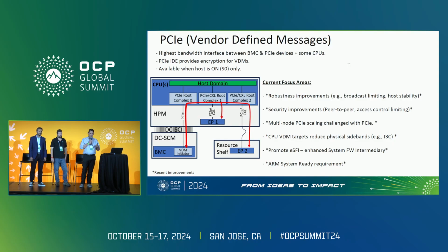Historically, in the ARM world, going back to ARM servers in 2010, it's all been this SSIF, which is, I think, a 400 kilohertz I2C bus for all host to BMC interfaces. Well, imagine the things that are happening here that you're wanting to exchange between BIOS, UEFI runtime services, and OS applications or whatever, through that neck down. So we're working with companies like ARM for the SystemReady requirement and trying to make sure that even ARM SoCs can start to make that available as an option.